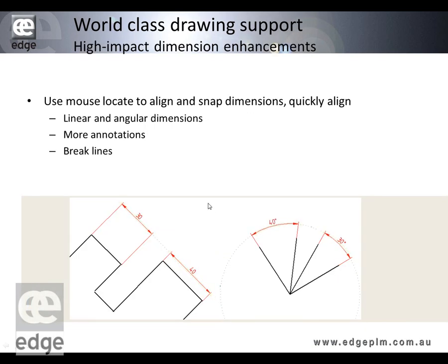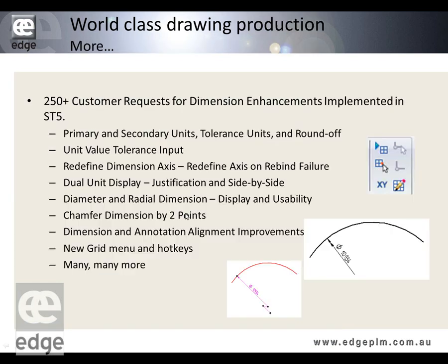This is a little thing, but something that's been with us for a long time, being able to very easily line up dimensions. Now, there's been all sorts of schemes proposed, and we've been able to use grids and things like that, which personally I detest grids. What we can do now is line these dimensions and annotations up just by touching with the cursor. So we move across, touch the other dimension with the cursor, and they lock together. We'll see that as well.